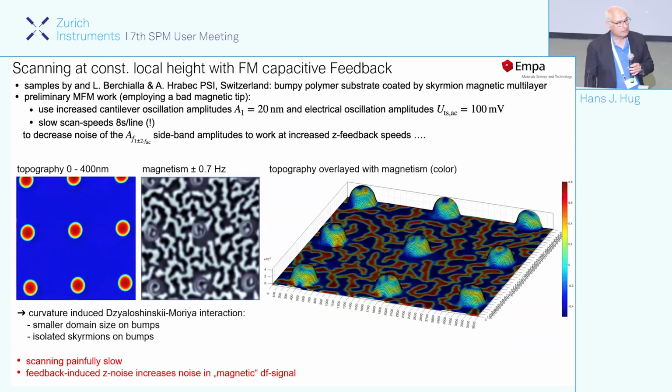Now, can we also measure non-flat samples? Yes, of course. It gets more challenging because this tapping lift mode doesn't work. So we have to have, again, a non-contact mode. And we use this sideband now to have a local feedback. So we really locally follow the topography.